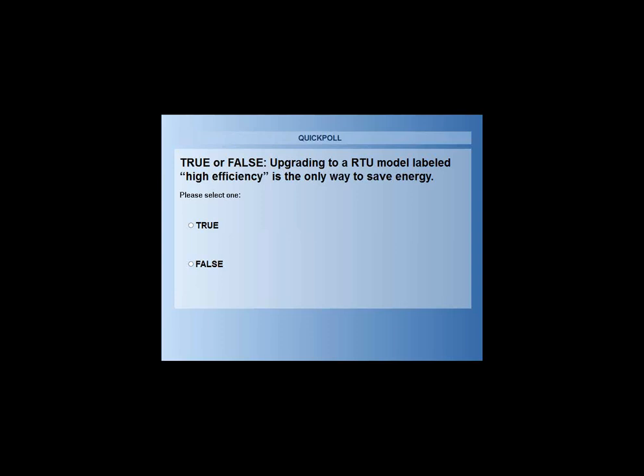Boris asked a great question. What is the ventilation requirement during unoccupied mode? During the unoccupied scenario, when nobody's at the building, you are allowed to ventilate down to 0%. So you shut all the ventilation dampers completely.